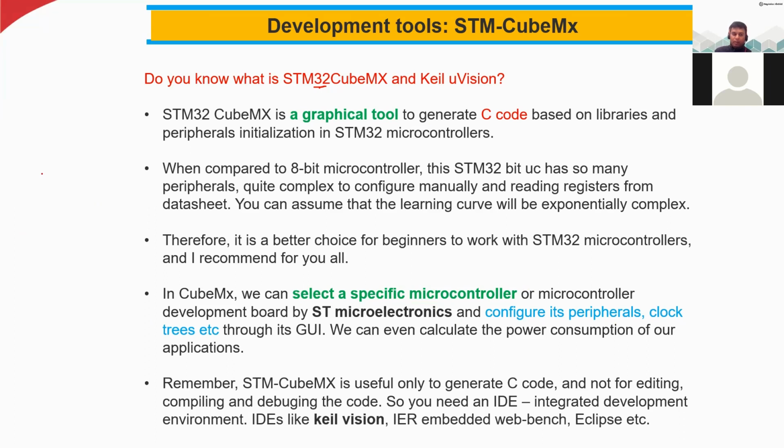You have to configure the RTC, real-time clock, and then the crystal clock or CC. And also you have to configure other peripherals, the GPIO, general purpose input output registers. And you have to also configure ADC, DAC if you are going to use them in your application. So it's based on the application code you are going to create. Everything you do in the GUI, the graphical user interface, instead of doing C code programming.